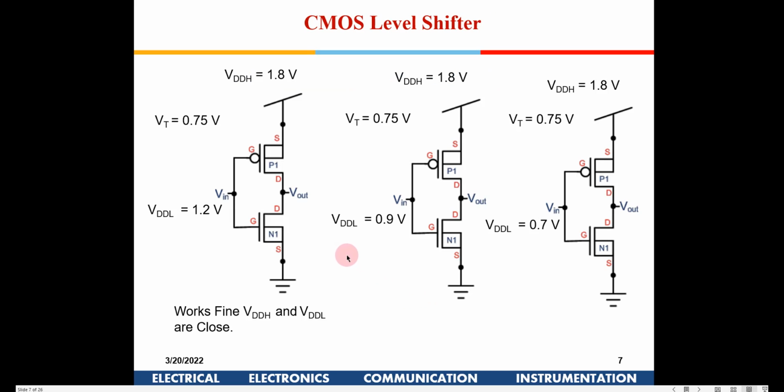Right. Now, there will be certain requirements where, within CMOS also, different VDDs will be used. Suppose we have some circuit which is operating with 180 nanometer technology, so the VDD will be 1.8. We can have some part of the circuit, say on the PCB, some chips, which are operating at, say, 1.2 volt, which is 90 nanometer or 45 nanometer. So there will be a requirement to boost up these signals to that. Bringing down the voltage levels is easy, right?